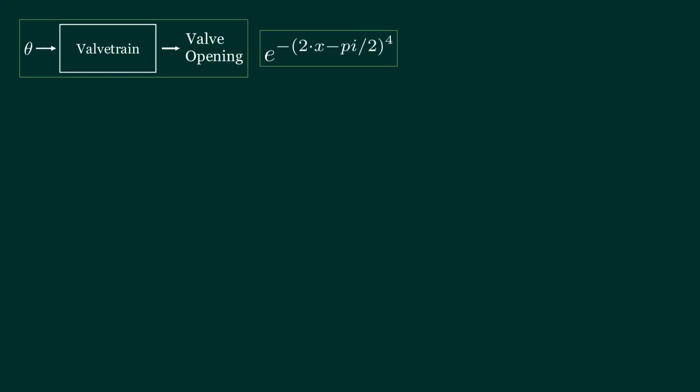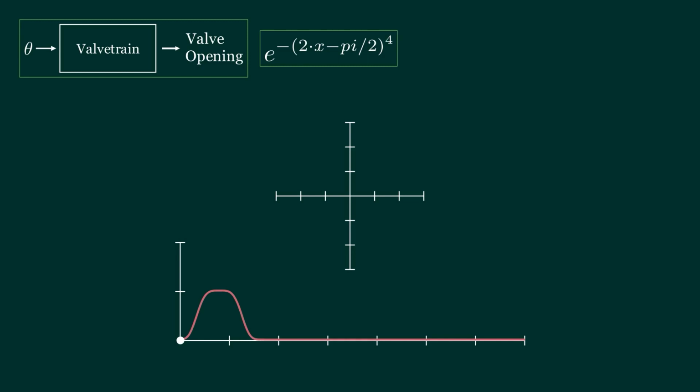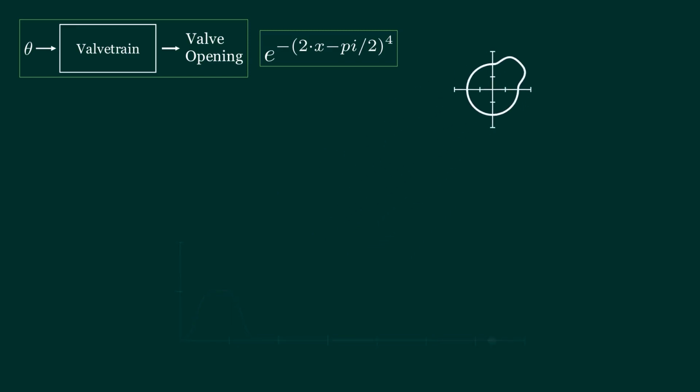Let's redraw the equation and convert it to the cam profile. All we have to do is change the x-axis with the angular coordinate and set the y value to the radius of the polar plane. Because our equation gives just an offset, we sum the value with the camshaft radius, which is 2. Now it looks like a cam. Let's see how it works right away.